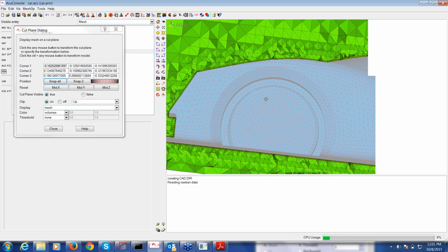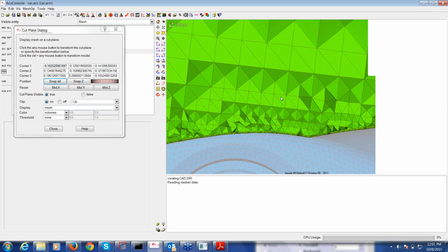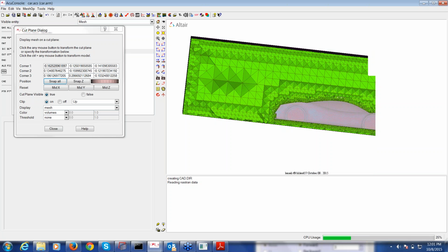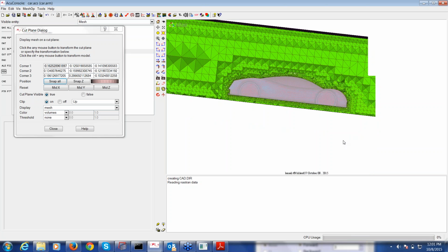But after the mesh zone refinement, the size is very huge. So you have to make sure that you do the meshing appropriately and don't use so coarse a mesh. You have to make sure that you have a very fine mesh. Even minimum, you can build around 3 mesh zone refinements, making sure that your mesh is very good there.